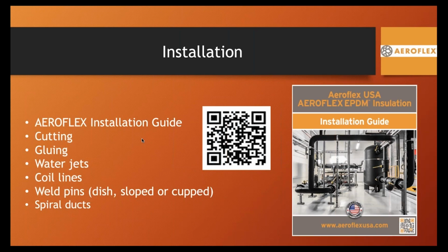the insulation. And regarding spiral ductwork, easy to do for wrapping, but when internally lining with our product, that is not the focus of the applications. Talking to sheet metal shops that have installed a lot of elastomeric, this comes up once in a while, and their rule of thumb is on 12-inch spiral pipe and larger.